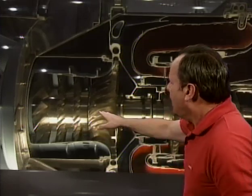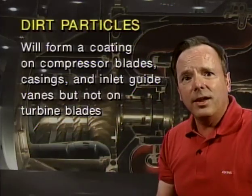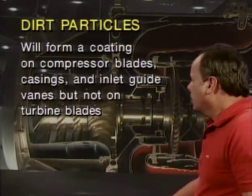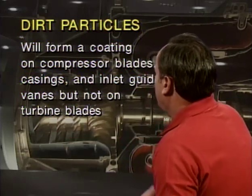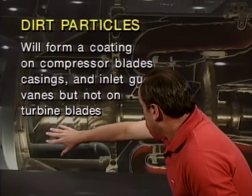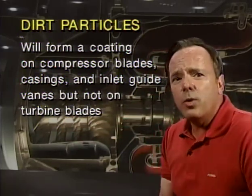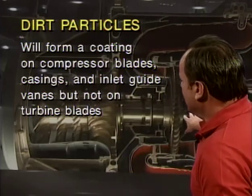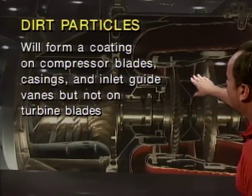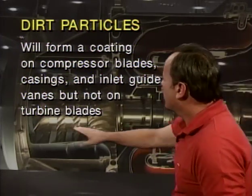Now, once again, looking at these compressor blades, you want them to be clean, and you don't want them contaminated in any way. Well, if you had dirt particles in the air introduced to the compressor section of the engine and in the inlet guide vanes, then that would contaminate those blades. But they're going to ask you, would it form a coating on the turbine blades? And the answer is no. These turbine blades are really in a high heat environment. It's going to burn off any coating, so you would not have a coating on turbine blades.